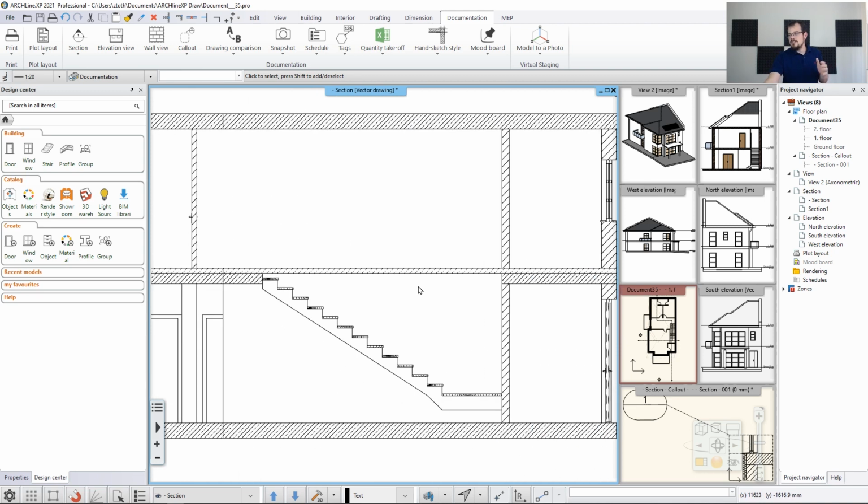So if you add an additional layer to a slab, the additional layer has no idea that it has to inherit the cutout, the recess over the staircase. So you have to amend that manually. You might have to do that. So how do we do that?